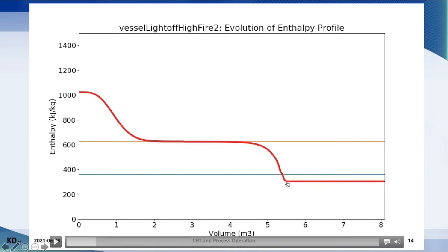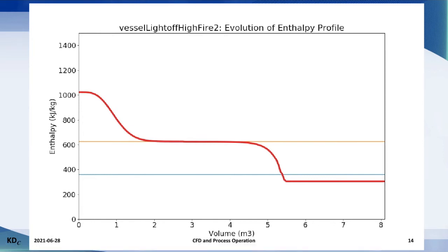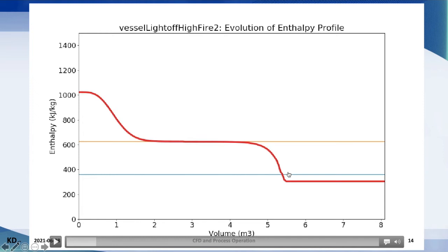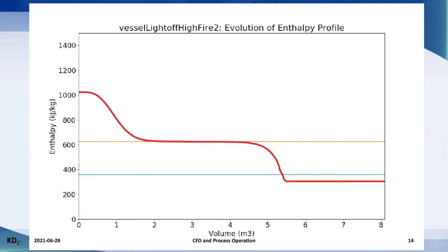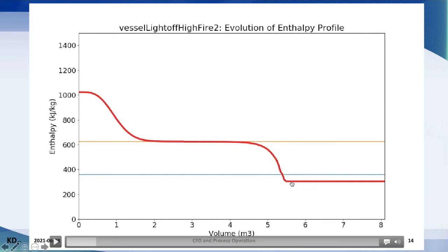The first step is from the initial condition of 40 Celsius to the bubble point of 57 Celsius. This moves across the bed rather quickly and reaches the outlet at time 570 seconds, or about 6 minutes. Now, all of the volume to the right of that point is liquid hydrocarbon.